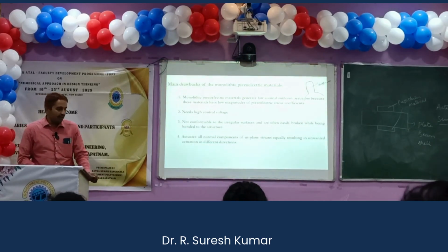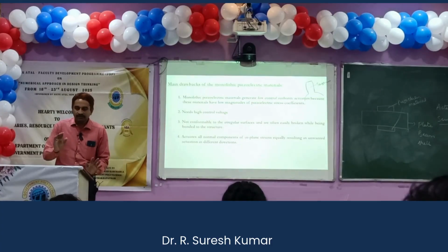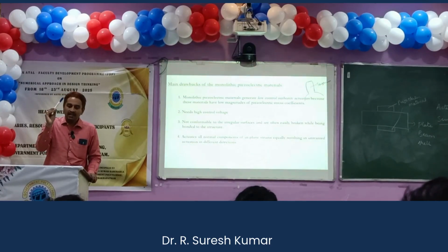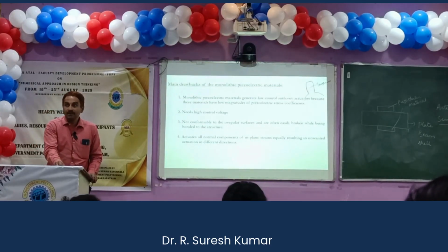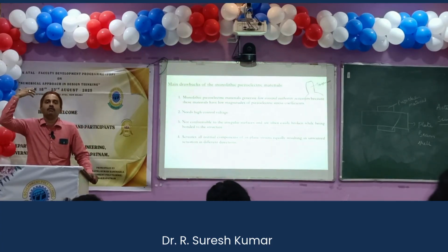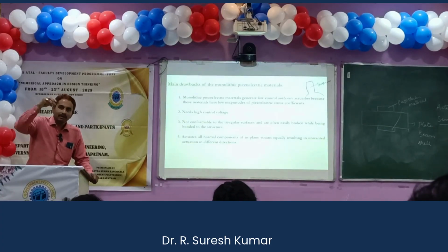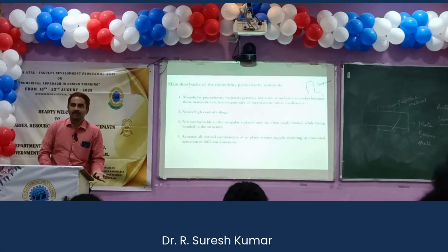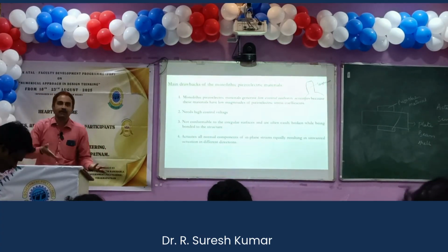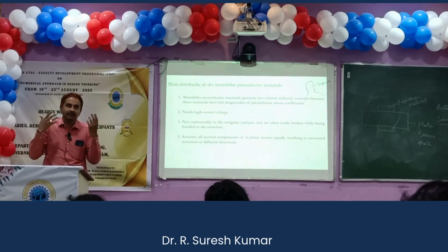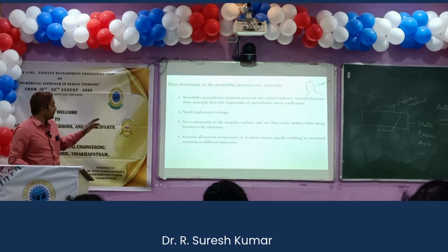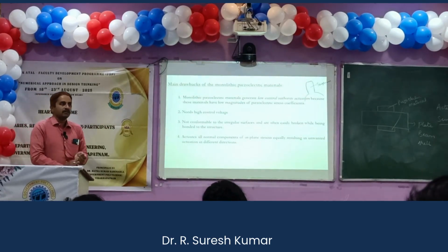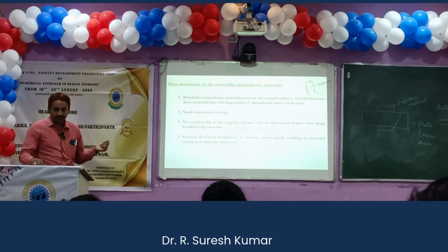So to say, for example, if this pen is made of piezoelectric material and you want to move it 1 mm, then you have to supply 20,000 volts of electric input, and then it will move 1 mm. Is it reasonable? No. For moving 1 mm, supplying 20,000 volts is meaningless and unreasonable. That's why monolithic piezoelectric materials are not advised for use in commercial applications.